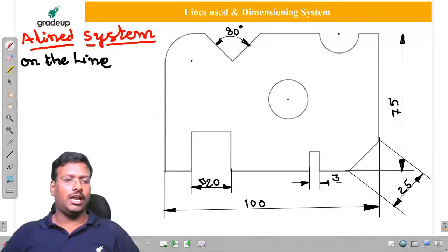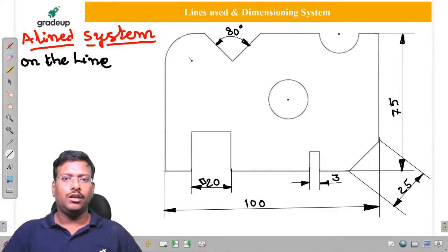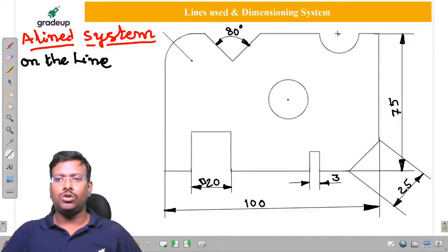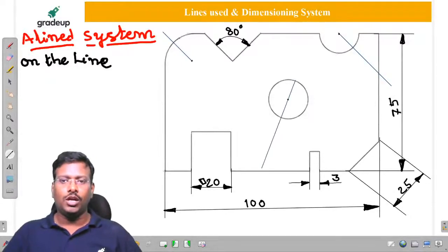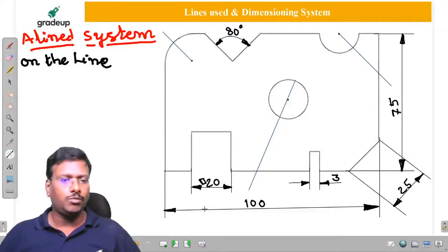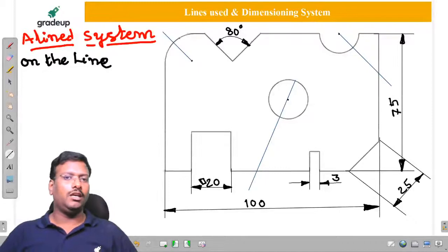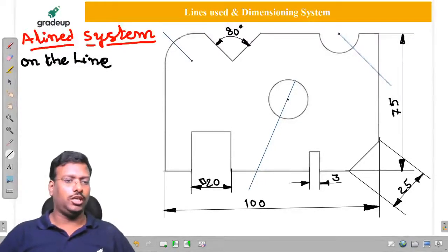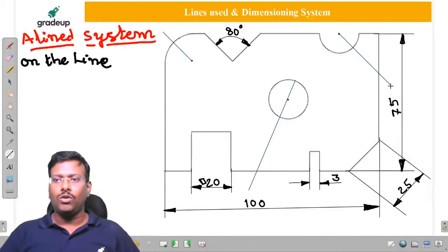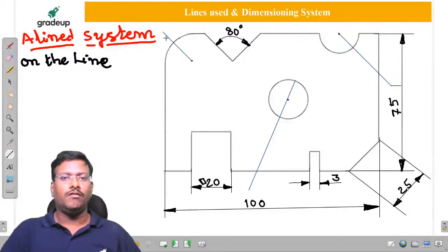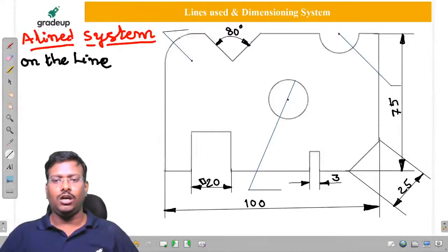Let us consider the ladder line. How we have to draw, I am going to show here. So from the center, we have to draw the line like this. It should be more than 30 degrees. Here also, it should be more than 30 degrees, but it should be away from it. So in this case also, it should be more than 30. Are you observing, my dear friends? It should be more than 30 degrees, but less than 60 degrees. Now, afterwards, we have to draw one horizontal line. Whether it is a left side or right side is immaterial, we have to draw a horizontal. Here also we have to draw a horizontal.